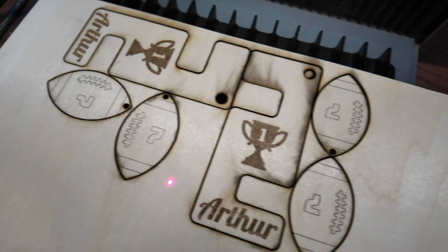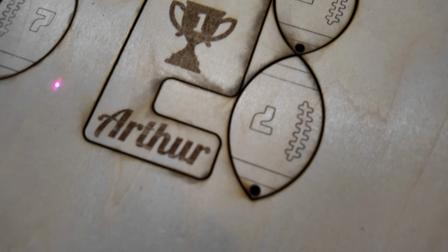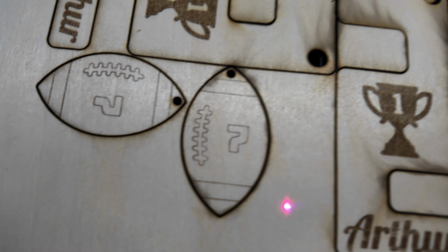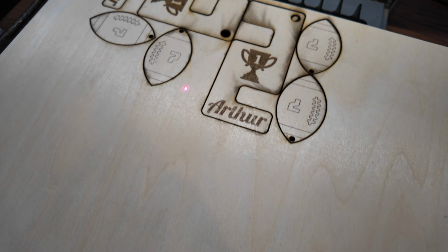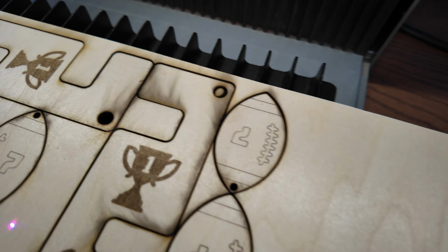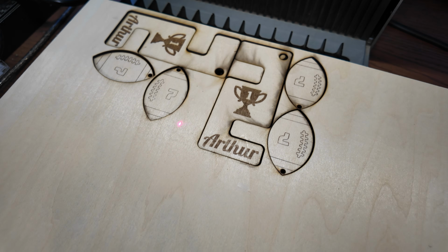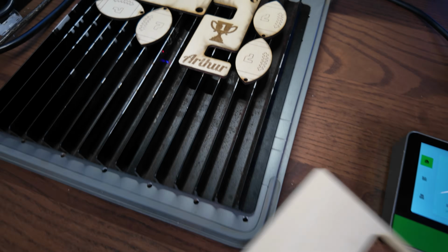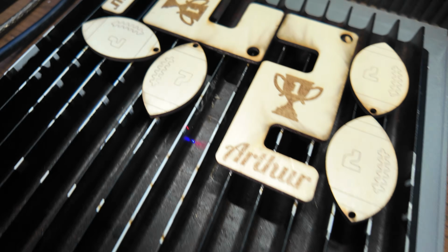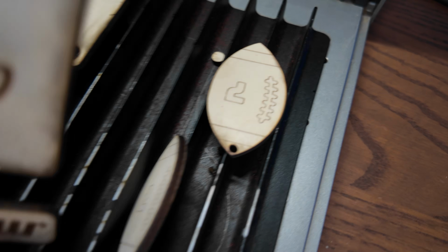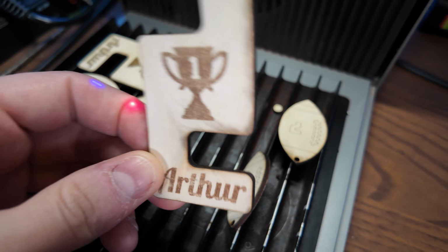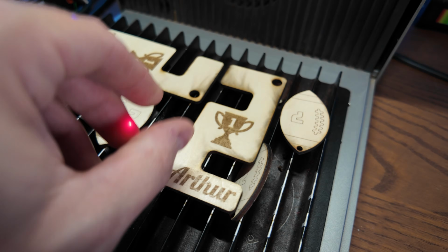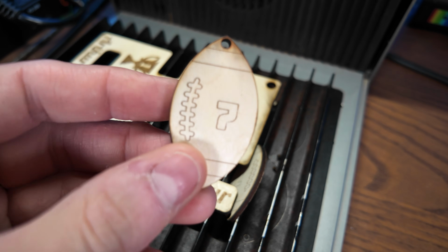These are the default settings. I think it did 6 passes on the cuts, and you can see that is way too much. So this is the importance of doing your own material and cutting tests, just so you can actually get the right settings. But I know this is going to pop off because 6 passes, there's no way it wouldn't. But there you go, look, it has actually done every single one of them, and it has done all the bits. We would need to clean these up because they are a bit charred from obviously our 6 passes. However, it's done a great job.